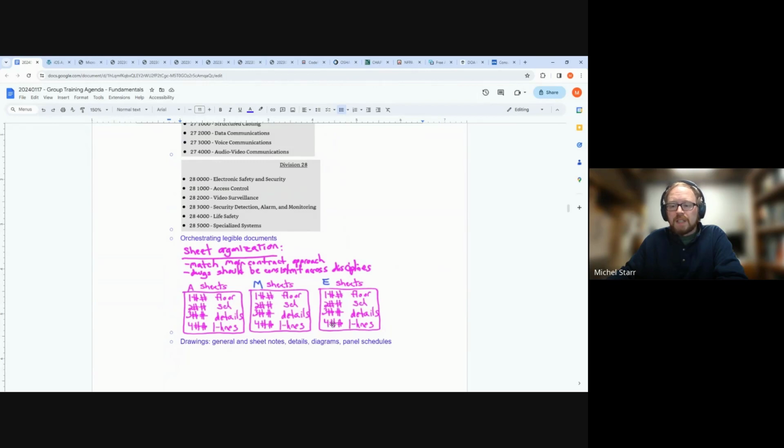There's a lot of miscommunication potentially in what was put on the paper, or there may not be products that can be obtained. For example, a UPS at 800 kVA could be possible to get as a 4-wire, so to have a neutral and the 3 phases on the output. But maybe at 1200 kVA, no. So it's making sure we issue things that are constructible and aren't perfect projects.